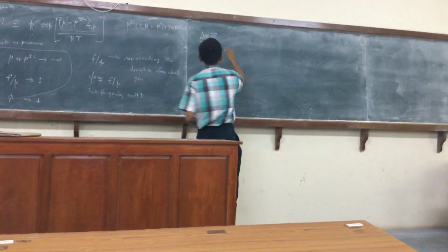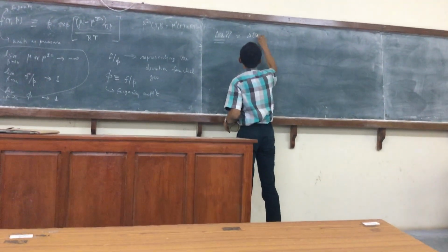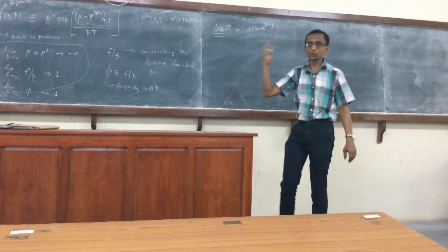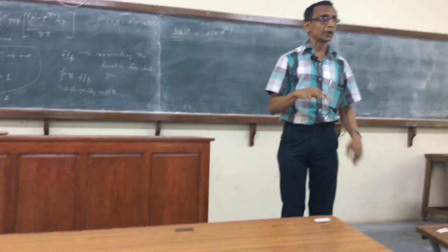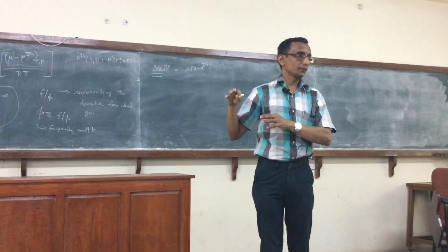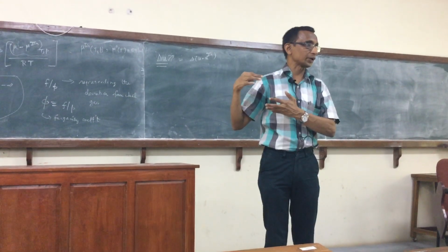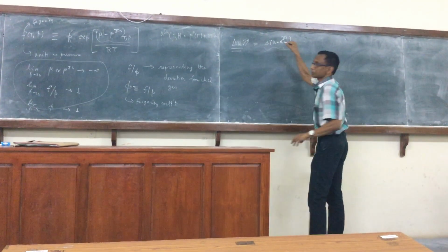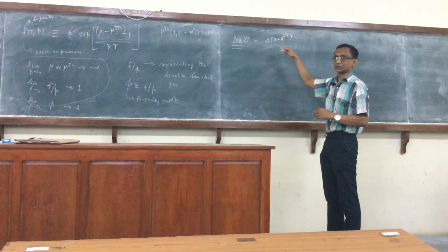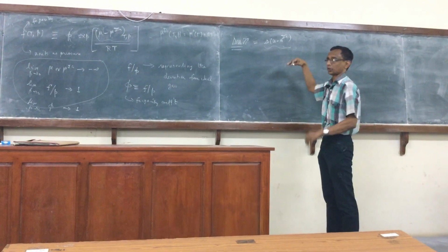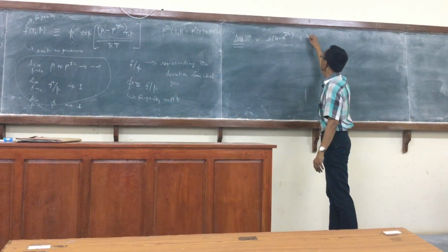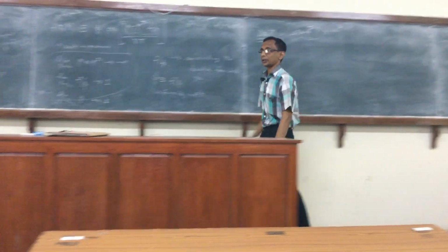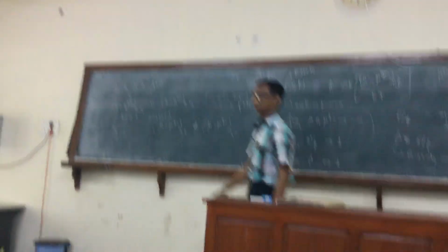So we separate this calculation of the change between two equilibrium states of any property into two parts. We divide the calculation of delta U into two parts: one which involves the difference in the departure function corresponding to the two states, and one that involves only the ideal gas property. That's easy to handle.